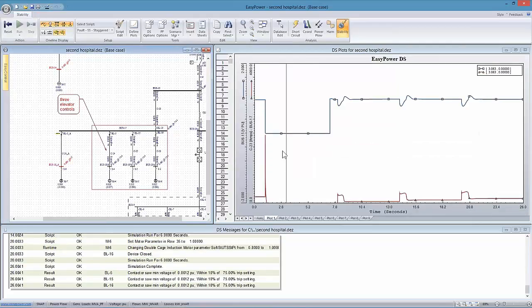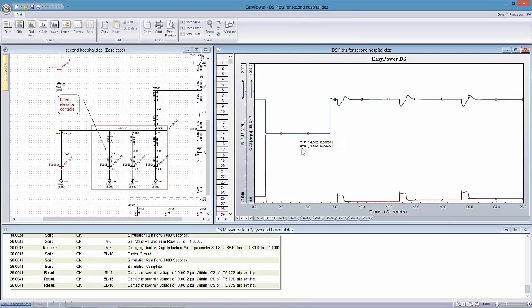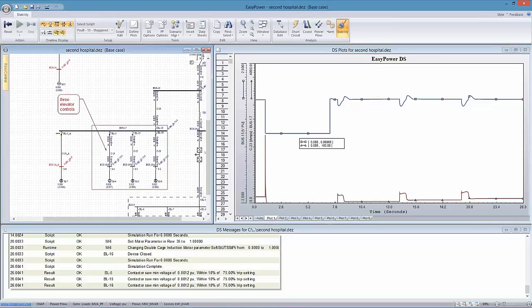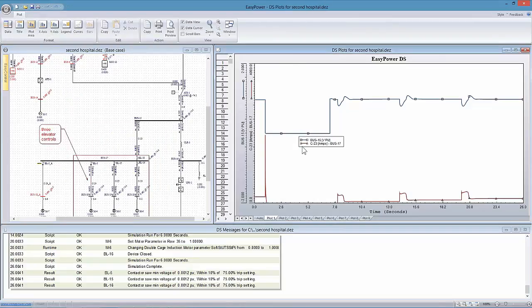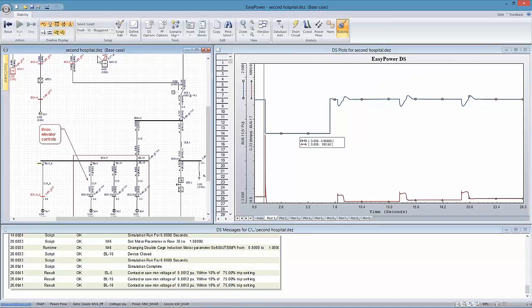And what we're seeing here now is we've plotted the bus voltage and current on the C23, which is this system right bus 17. All right, and so you can see with our extended time separation, we don't have any problems bringing each of the motors up to speed.